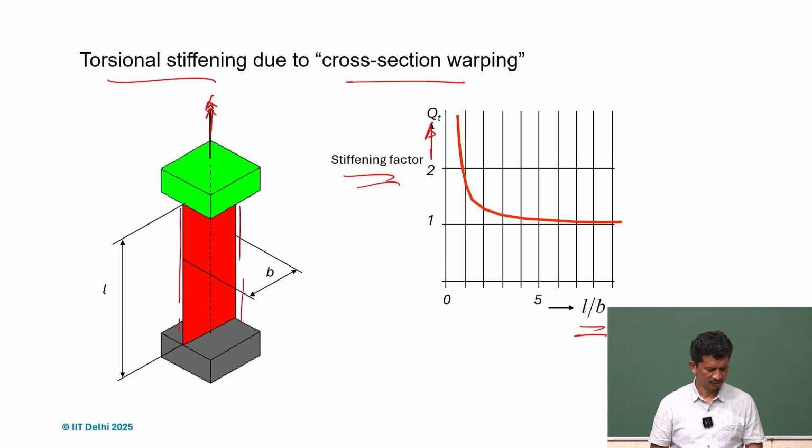It means the outer edges will get stretched, and the inner part, the axis, will get compressed. So they will start fighting, and definitely because of that, since there is a huge compressive load, there will be warpage, and yes, it's also a kind of buckling phenomenon, and we cannot use it anymore. So this deflection is very limited.